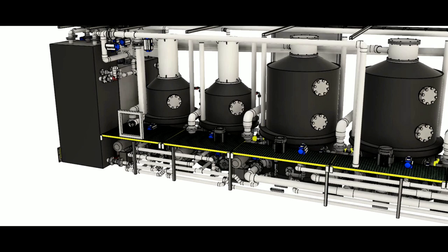Those units fill up, they run through their own automated processing cycle to dewater the primary fractionate and to further concentrate it. So on the right-hand side there, as we said in the video, you're getting about a 10 times concentration step, or a 10% wet cut. But in this secondary stage, that's when the real magic happens. And that's where the patent lies and the innovation, I guess, lies, is that we're able to get 1,000 times concentration step in that secondary fractionation step.